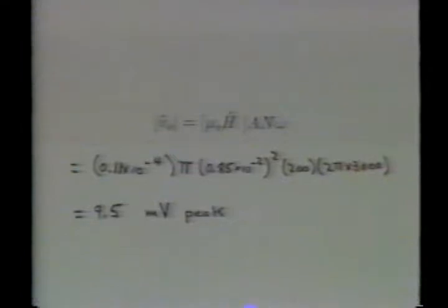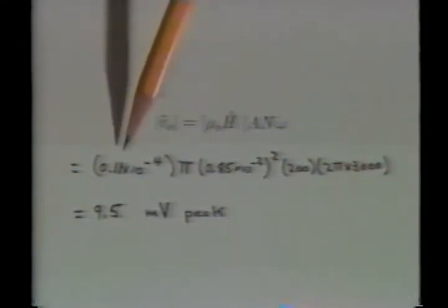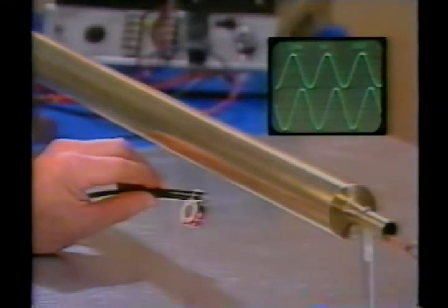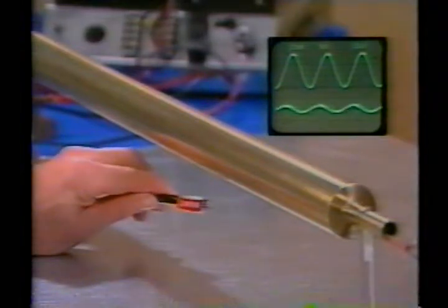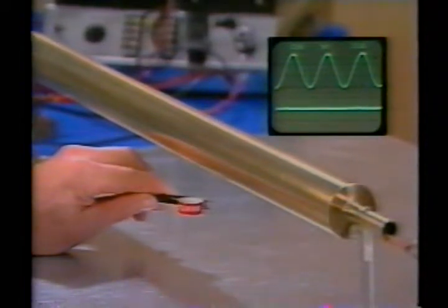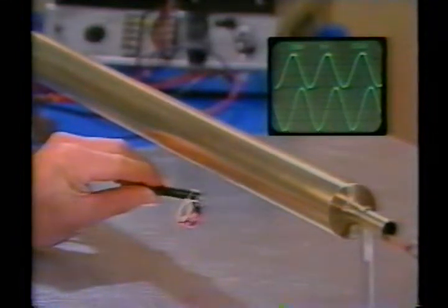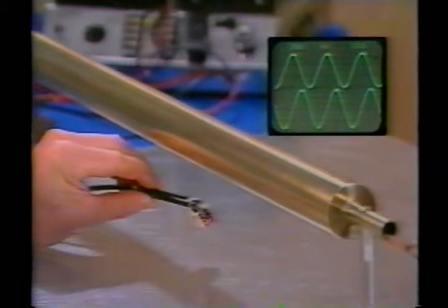Here at the center line, the tangential field is horizontal, just because of symmetry. Let's see if the flux density normal to the conducting sheet does tend to be 0 off the center line. Here to the side, the normal flux density appears to remain small compared to that tangential. So the current is returned in the sheet with just that distribution required to make the normal flux density small.